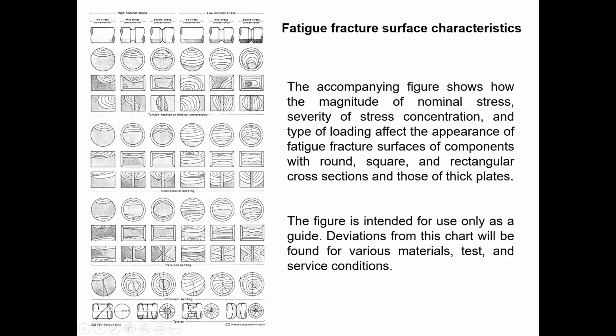Brittle. It's brittle. This one, that's ductile. Okay, what is the reason for this being brittle and this being ductile? Because the brittle material will have a more sharp cut, and the ductile will have a sort of elongation and then a snap. Okay.